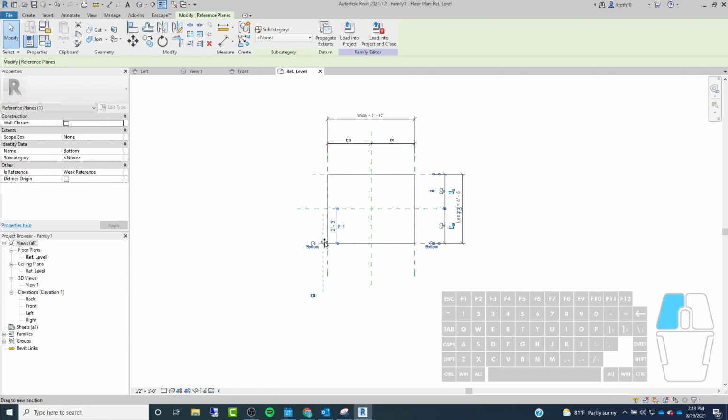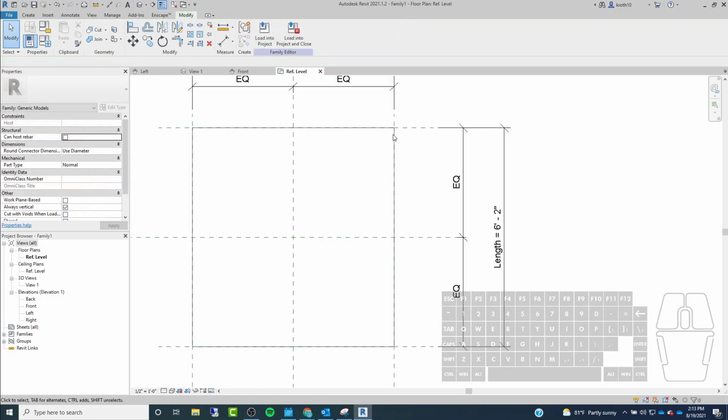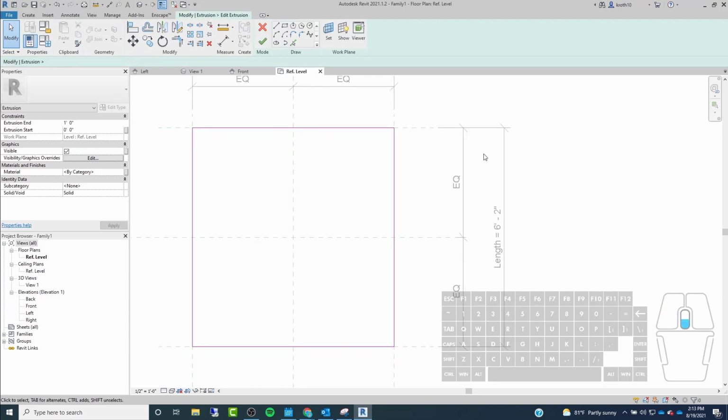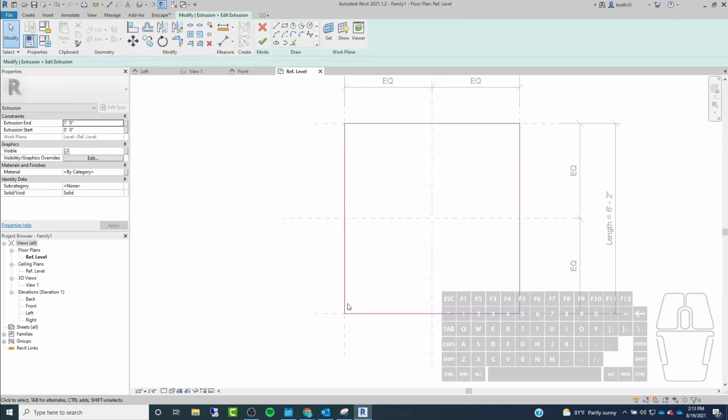All right, so going back to the actual extrusion, the next step would be to add in those little fillets around the edges to make them rounded. So to do that, we can go to our fillet tool.